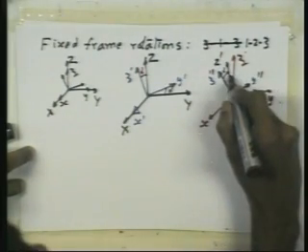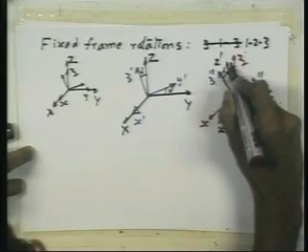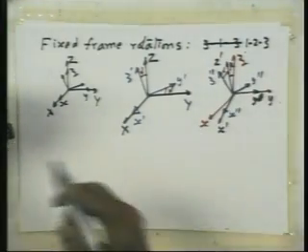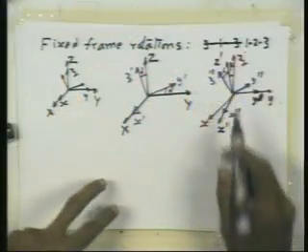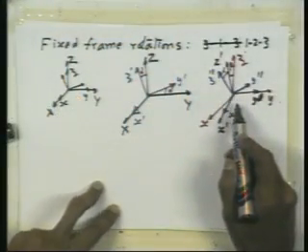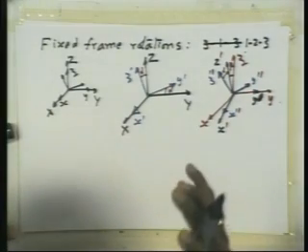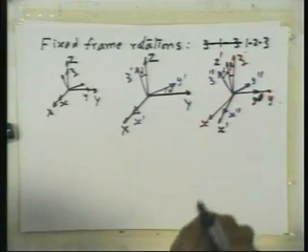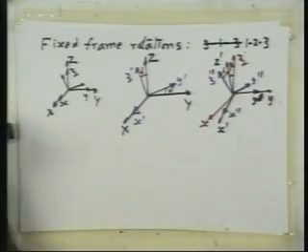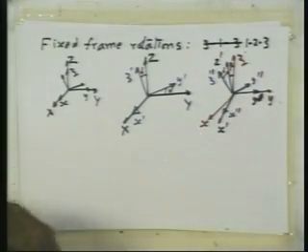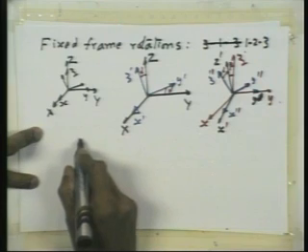Now this is beta. Okay. Now what I do is rotate the whole stuff. Rotate this particular frame x, y, z about the global z direction, and while it rotates, it takes along all the other reference frames as if they are rigidly attached to that. Fine, that is what is important. So if I do that, I get the following.